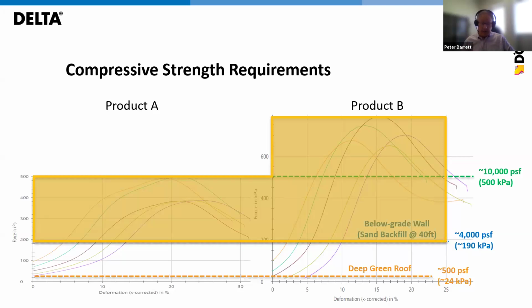The results of the analyses may also be used to compare the relative compression yield points of materials that exhibit a detectable compressive yield point. It is anticipated this test will be used for quality control testing to evaluate uniformity and consistency within a lot or between lots where samples and the geometry matter.